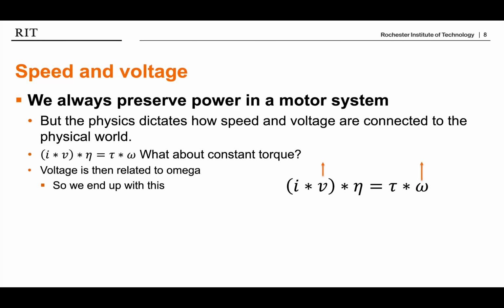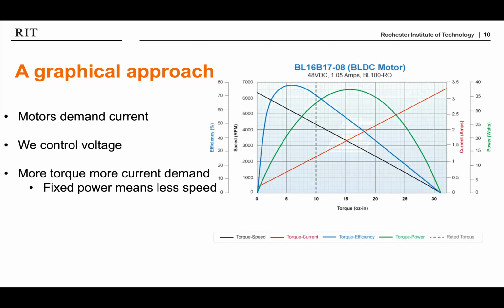All right, so all of this is good, and I want to design a motor, or maybe I want to select a motor. Do I have to sit down and go through a whole bunch of equations to calculate current and voltage and torque? Maybe I have to do a dynamometer thing, build something that can measure these. Well, as it turns out, provided you're willing to spend enough money to get a good motor, it will be provided with something that looks like this. And this is what we call a performance curve, or curves, or sometimes a performance plot, depending on who you are and what your industry is.